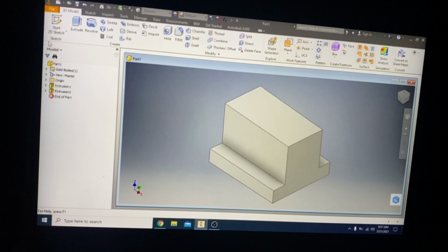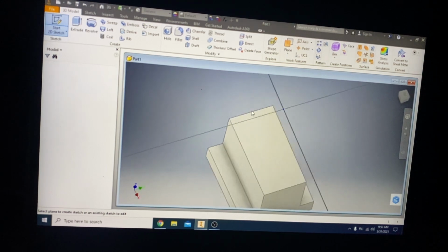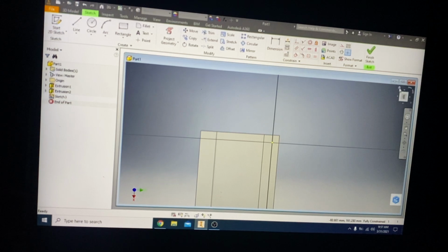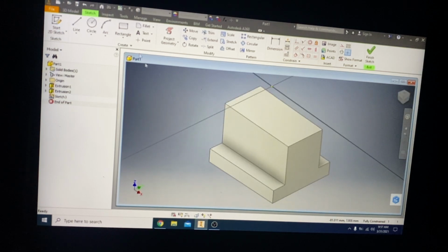So now what I do here is, instead of drawing, I go down again from this point, or I can go to the top view or in the front view. It doesn't matter. So I go to the top view in this plane. So now I go to the home button. Now I go and draw a rectangle. Now how to draw the rectangle? I will draw it from the middle because I need to have a hole which is 20.